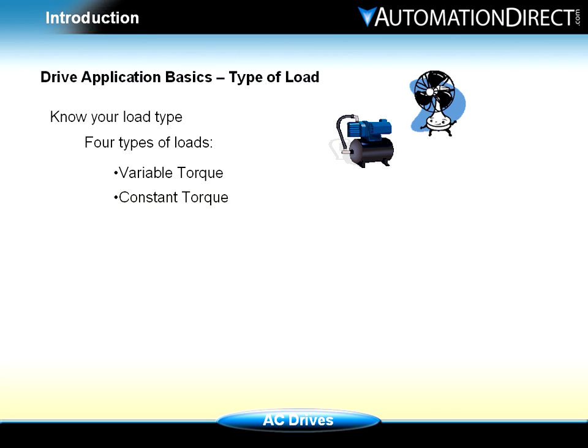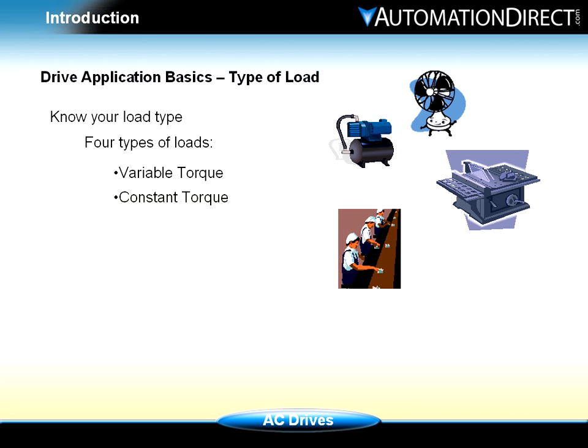Constant torque loads, which require constant torque at speeds up to rated base speed. No matter how fast the load is being moved, the amount of torque does not change. Some example applications are conveyors, machine tools, cranes, and elevators.